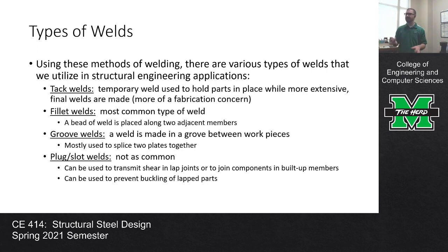And so once you finish your tack weld, you go and you measure it again to make sure, okay, is it in the right spot? Do I need to move it? Because if it isn't, if you have to adjust it, you can grind that weld off and reposition. So you always tack it before you deposit your real weld.